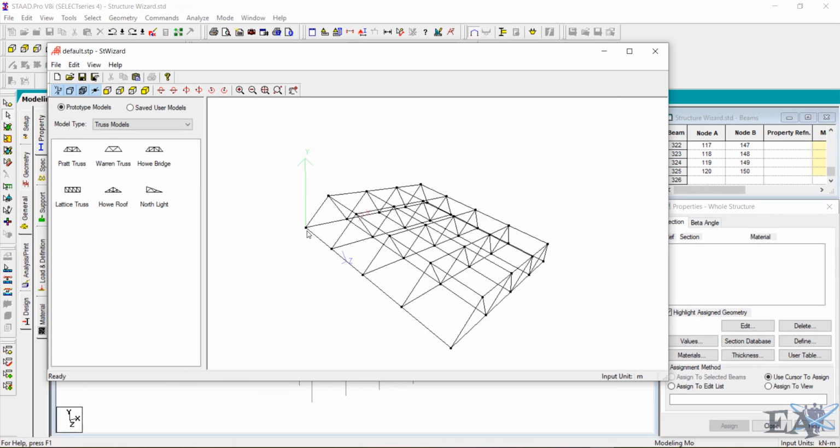Normally in trusses these nodes are always connected, they are not free. Before the truss is placed in its actual position, all the trusses are separate, and once the trusses are placed in their position and bolted to the beam, after that they are connected with the pipes so that they are much more stable. So if you want this kind of truss, you can define it this way.